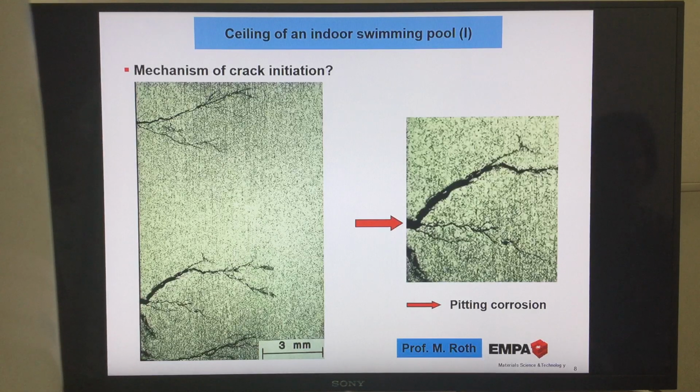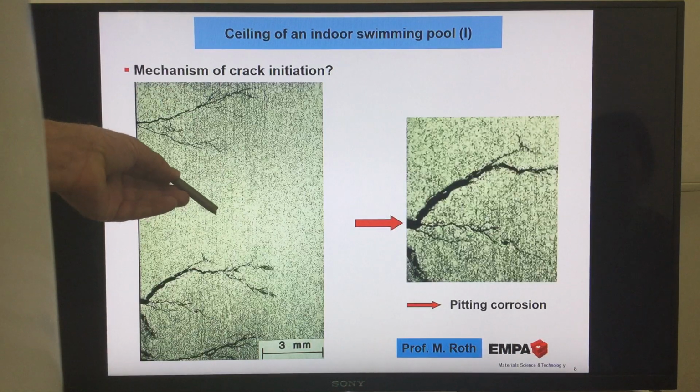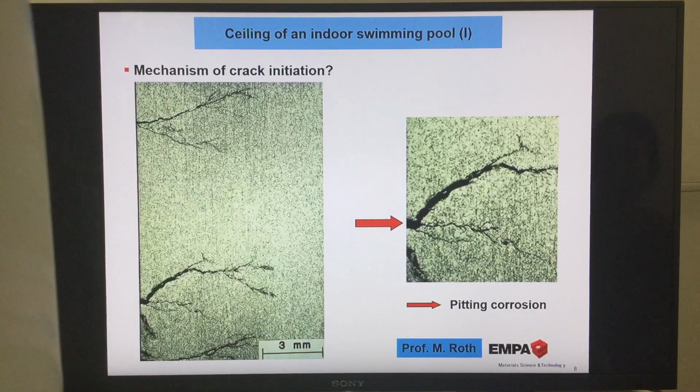The dislocations are responsible for plastic deformation. So when plastic deformation starts, there will be more and more dislocations on these slip bands. And when these dislocations meet on the slip bands, the surface, there something very strange can happen.